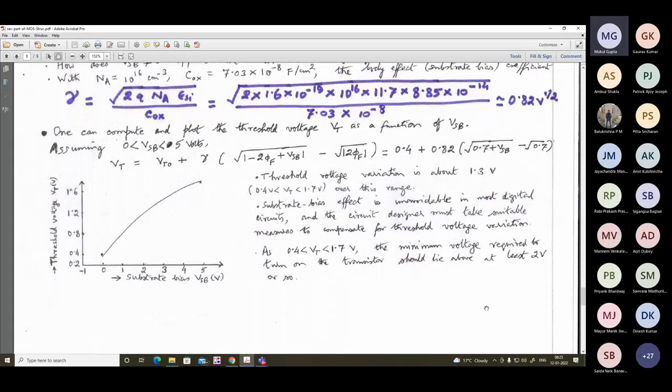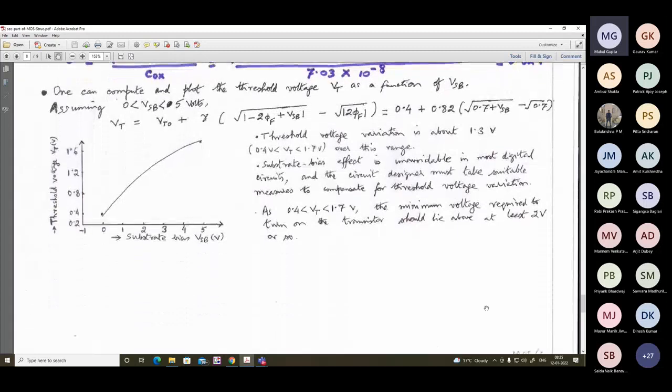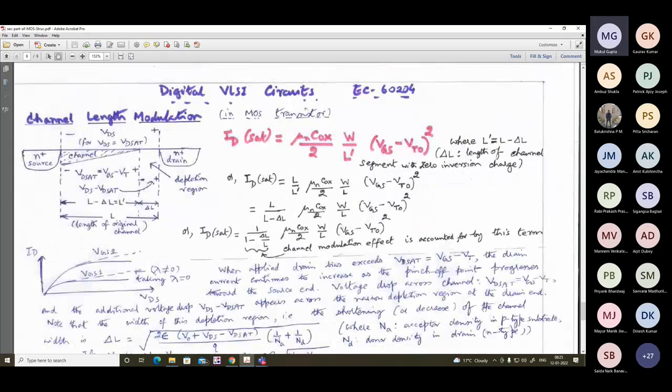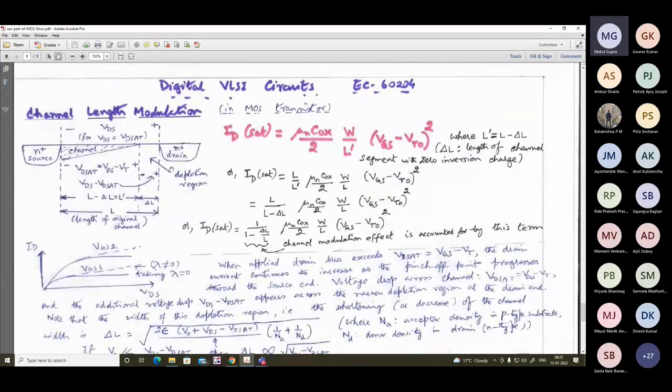Next, what we see, briefly we note. As we come to take into account the transistor, say NMOS transistor, it consists of two isolated islands of source and drain. So as the majority carriers flow from the source to drain, it means the conventional current is flowing from drain to source. So VDS is there. That means the drain is positive with respect to source.